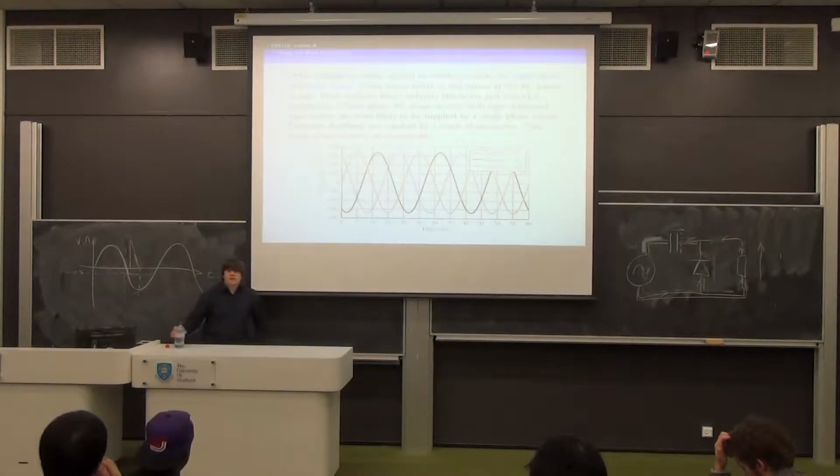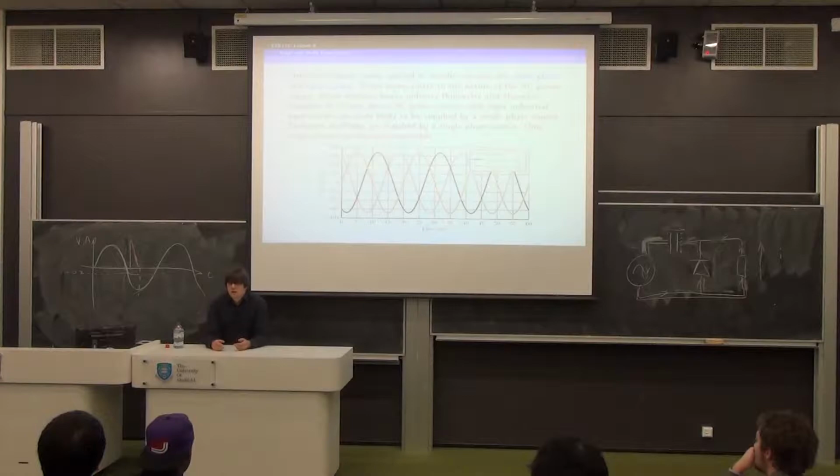well, if you were to get a motor and make some construction whereby you stop the rotor from turning, so the rotor is the turning bit in the middle. If you just grab it, the motor will try, and we'll assume the simplest situation where it's a DC motor supplied by some simple circuit. You'll find that there's only torque when there's current, and there'll only be current when your rectifier is conducting, because you've got some mechanism of stalling the machine. I wouldn't put your hand on it, it wouldn't do any good. The torque will come in pulses, and those pulses will make the machine vibrate.